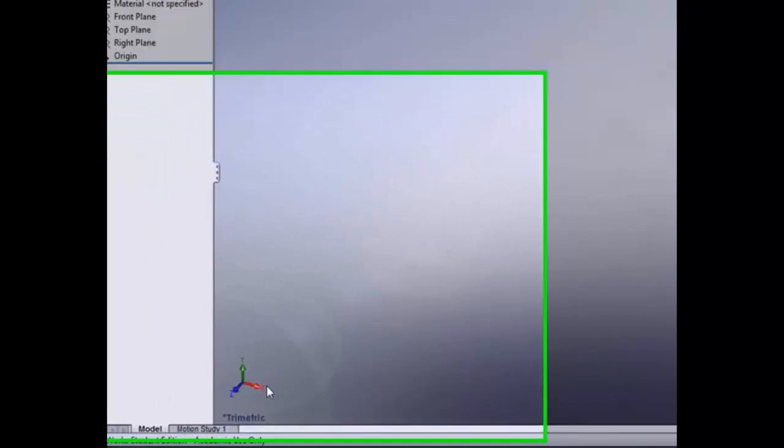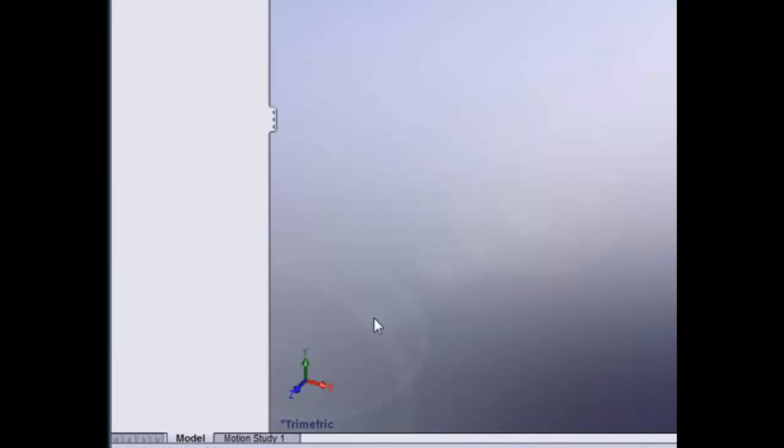First thing, this is your coordinate system. Unlike other modelers, Z, as you can see here, is pointing out of the screen at you. Y is actually pointing up. X is pointing to the right. Typically, when you're modeling, you're seeing something more like this in Rhino, where Z is up and Y is going away from you, and X is to your right. But this is not the way SolidWorks models. So just be aware of that, and we can talk about coordinating between Rhino models and this coordinate system.